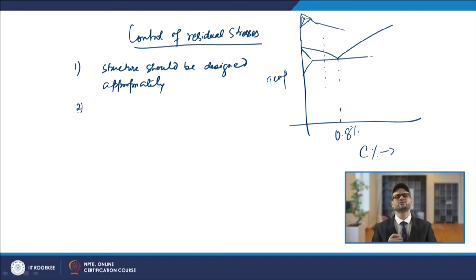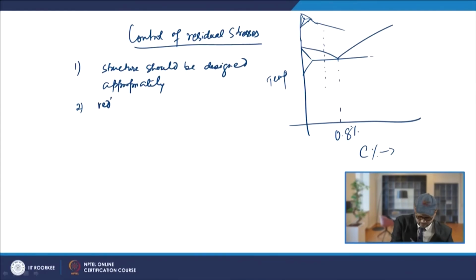So you should try to reduce the amount of weld metal, and that will also lead to a lower value of the residual stresses.